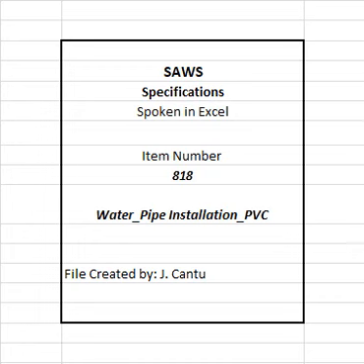G. Submit manufacturer's certification that PVC pressure pipe for water lines and force mains has been hydrostatically tested at factory in accordance with AWWA C900, AWWA C909 and this section. H. Submit manufacturer's allowable deflection. 3. Shop drawings. A. Catalog data sheets for all materials confirming pipe, fittings, and other materials conform to requirements of this specification. B. Pipe supplier information. 1. Submit company name, and contact number.